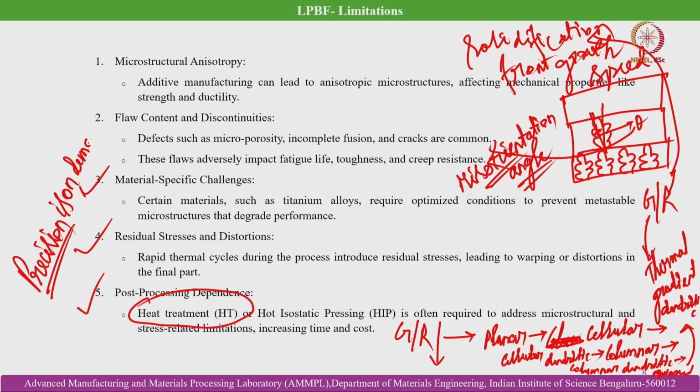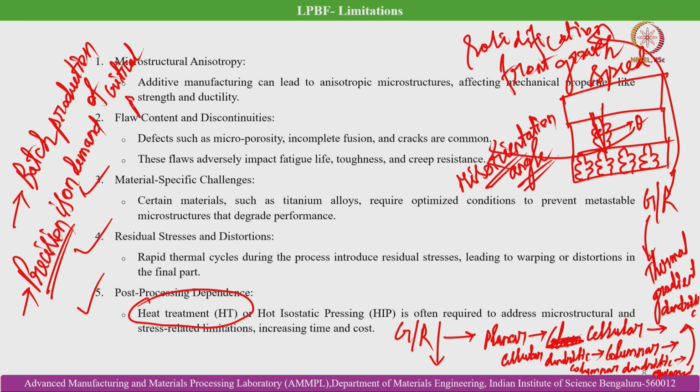So, when precision is on demand, and also for batch production of critical parts. The moment you need to move to mass production, then it is of no use to stick to AM; it can be moved to the conventional subtractive manufacturing techniques, where the cost can decrease with the increase in the number of parts.